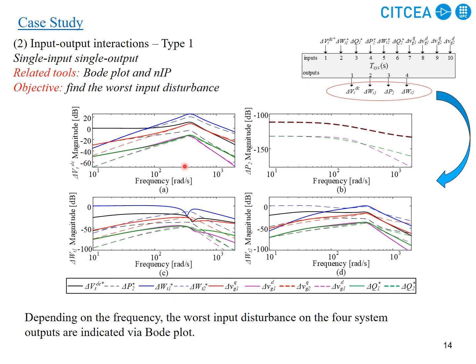So, for example, as a control engineer, it is interesting for me to know that for a frequency around 300 radian per second, which is not very high, I mean, at least it is near the fundamental frequency, I expect that if energy 1 and energy 2 have some change, maybe if something is happening in the MMC and total energy goes through some transient, I expect to see that on the DC voltage too.